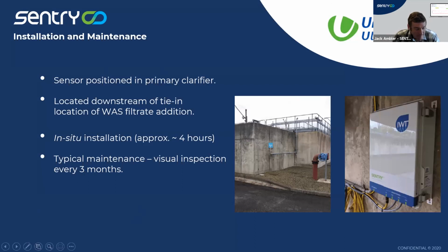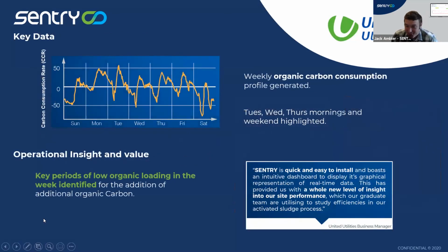Certainly there are pros and cons to both methods, but it was very interesting for us to get into that, work with this group, and get exposed to a lot of these data management experts from United Utilities. But yeah, just to tell you about the installation, the system installs at the primary clarifier, the effluent of the primary settling tank in the UK, and one at the effluent of the facility itself, or the effluent of the biological reactors. If you go to the next slide, there actually hasn't been any maintenance since the installation so far, but we've been getting really good data at the location, so it hasn't been a requirement.